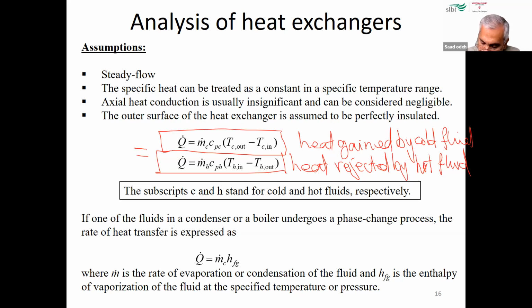So in a condenser, we are condensing steam. When we condense steam, the amount of heat of evaporation or heat of condensation is equal to the hfg, right?